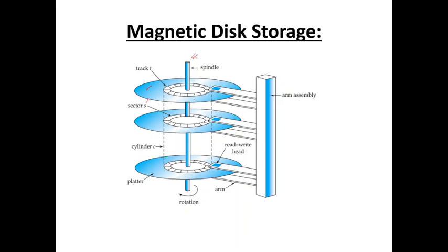And all these platters, on both sides, are divided into different tracks. Okay, and all these tracks are separated into sectors. So whenever we want to read any sector, any track, we have to move this arm to that particular track, and this head has only to and fro motion. So we have to move this particular head to the desired or target track.